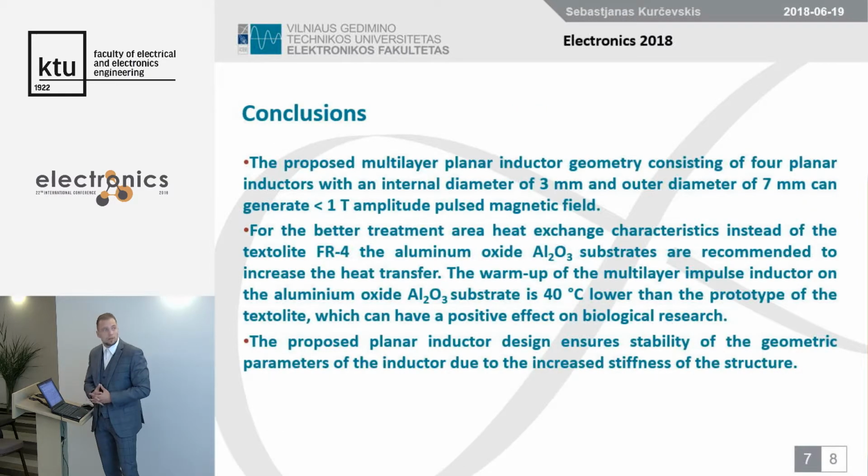And later on, regarding the conclusions, the proposed multi-layer planar inductor geometry consists of 4 planar inductors with an internal diameter of 3 millimeters and outer diameter of 7 millimeters, and can generate an over 1 Tesla amplitude pulsed magnetic field.